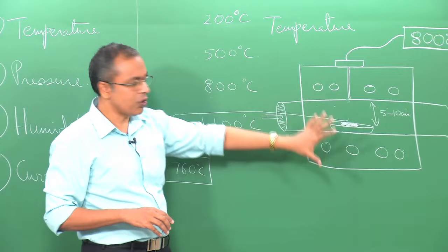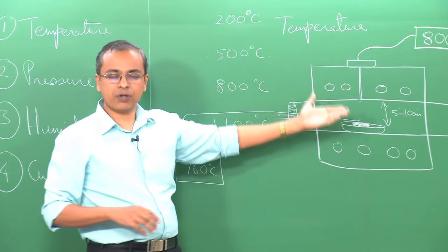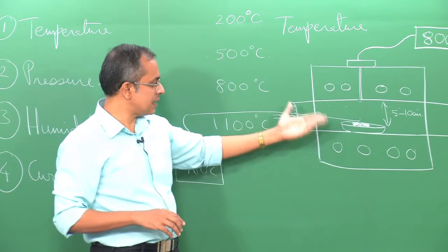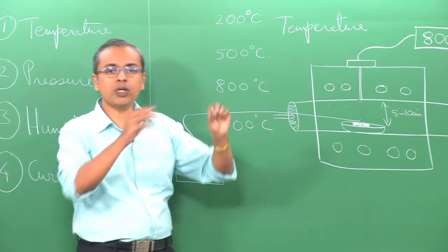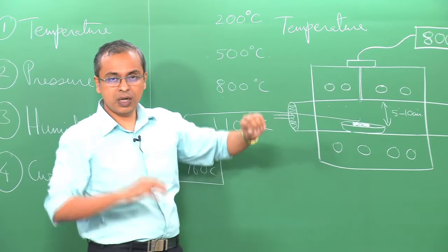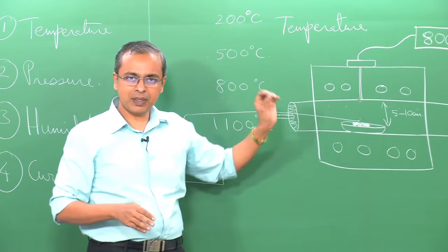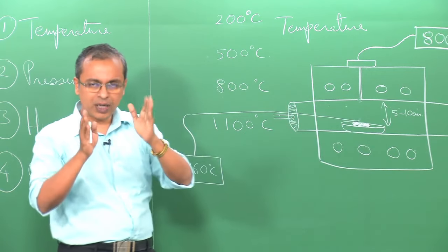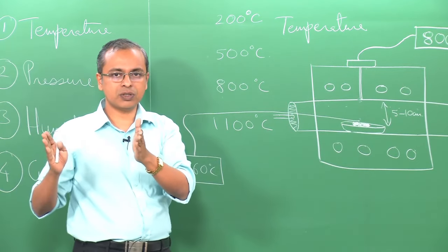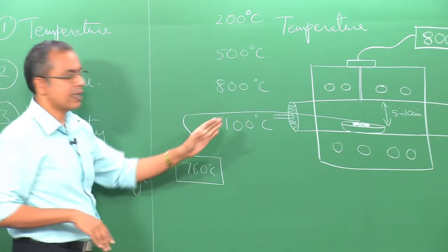You may have to think of what is the concept which creates the possibility of an error, and then compensate for it. So, you compensate for it such that the actual measurement, you know what is that actual measurement, so that you have eliminated the error, you have adjusted for the error, compensated for the error. So, in using some standard sample, using some standard test conditions, you figure out what is that error that occurs in your instrument. So, instrument related error can be corrected, and therefore, you are now making a good measurement.